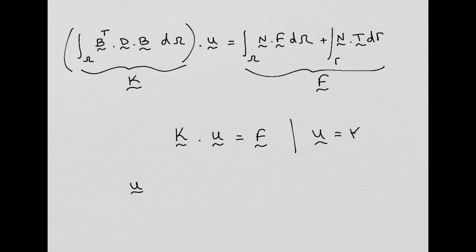Once you get the degrees of freedom u by solving the system of equations, you calculate for each element, at each integration point, the strain field by using the strain displacement matrix.